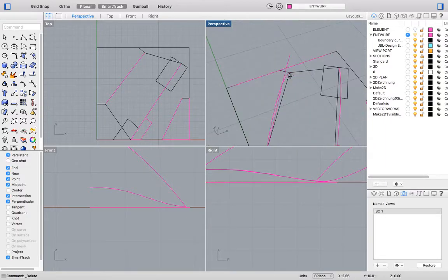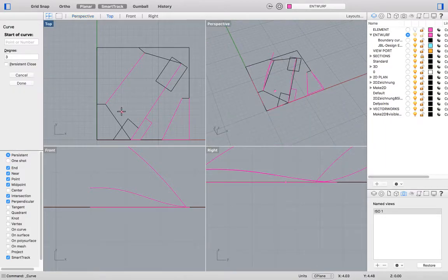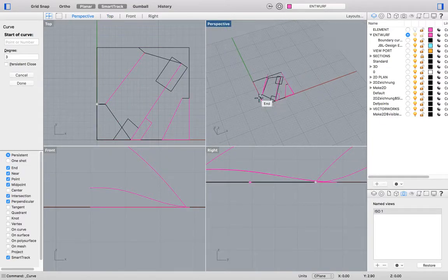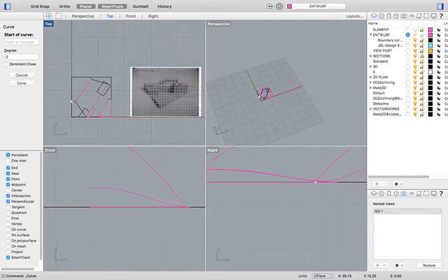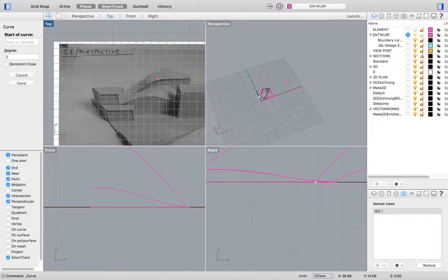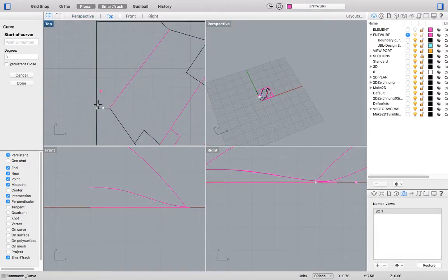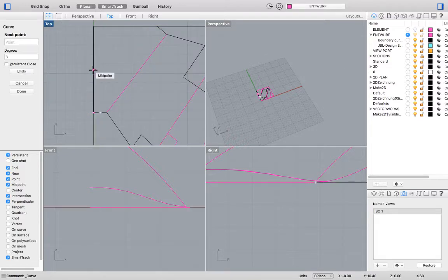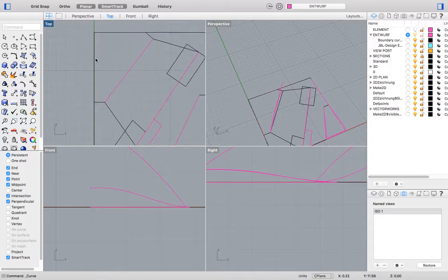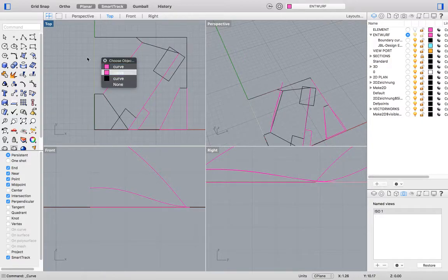Now we need to make the back profile curve. So looking at our model again, it's basically the parallel curve to this one. So let's create the control points first. 1, 2, 3, 4. Enter. Select the curve. Edit points on. I want to move those 2 points vertically.